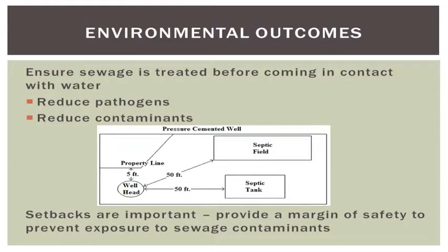So in a nutshell, what are our environmental outcomes? If you want to sum this all down, what do we really want to have happen with septic systems? There are basically two things we want to have happen. We want no exposed sewage on the property itself, and we don't want any pathogens or nutrients entering the groundwater. Those are the two outcomes that our whole program is geared to achieve. To help do this, we have design standards written in Chapters 7080 and 7081, but we also require setbacks to things that can be potentially contaminated, such as wells and lake setbacks.